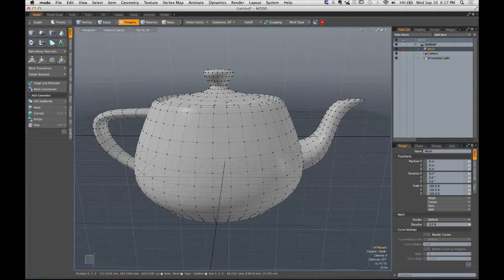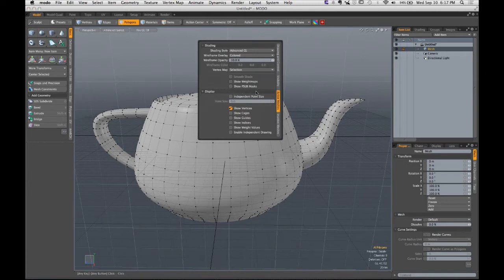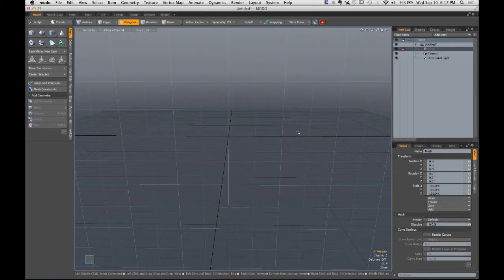So you have to turn the visibility of your vertices on to really see the impact and the difference between the two. So if you want to show your verts, which I encourage you to do, put your mouse cursor in the center of your OpenGL viewport and hit the O key. O as in October. And that's going to bring open your viewport properties. Under the Active Meshes tab, simply enable Show Vertices and you're on your way. And then once you hit the Delete key, the one over by the arrows, you can delete all the surfaces that are currently living in your scene.